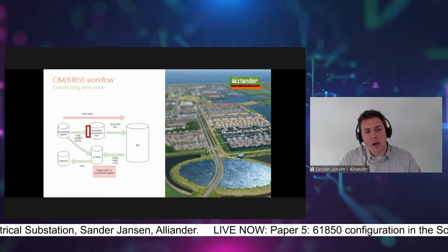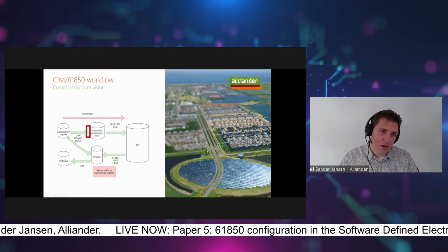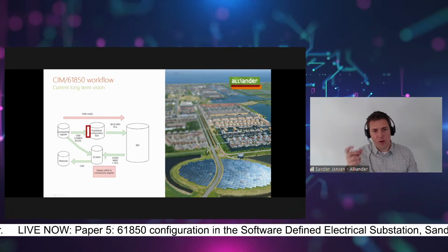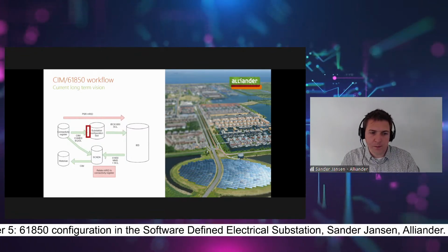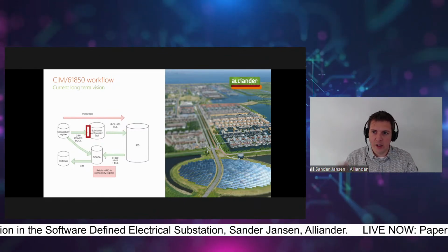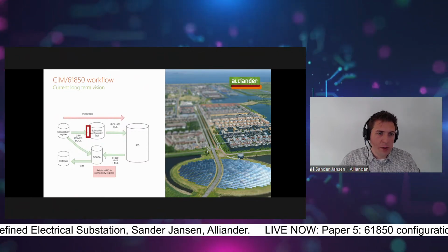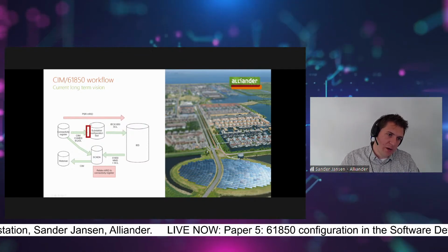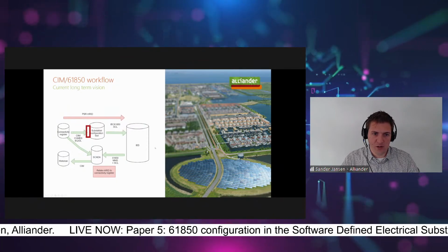And if you take the identification of CIM within your 61850 files, the SCADA system could use that to see, okay, this measurement point was here in the substation, or this function is running in that substation. Because currently we have some challenges in figuring out the data points and plotting them to the grid. By using this way, we can manage that in the long run. But what I want to show you is just that red box where we want to convert a CIM file into a 61850 SCL file.